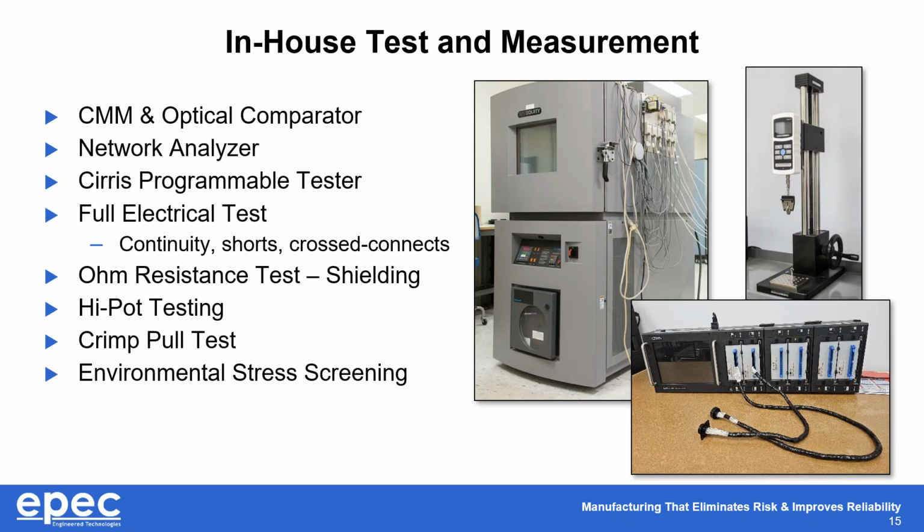Once the heater is built and assembled, we go through extensive electrical and thermal testing to verify that the heater meets all program objectives. Some of the most common tests we run are 100% high pot tests, thermal cycling, and even operating the heater at different environmental conditions like hot and cold to make sure that the heater is properly working.